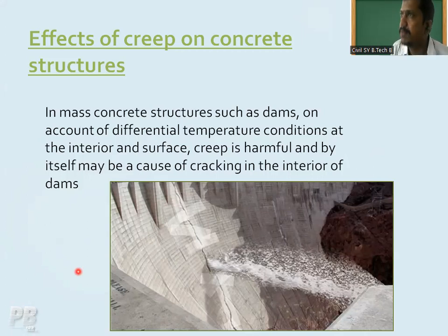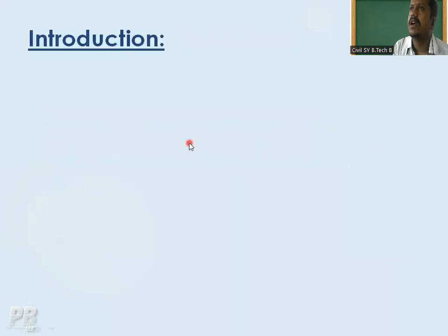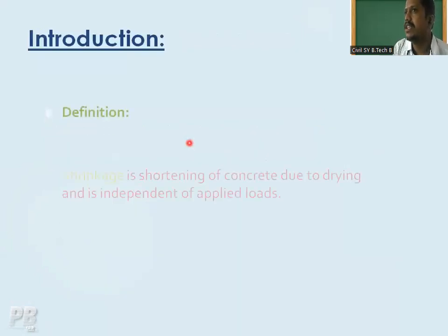But if you follow some faulty practice, there is a chance of early formation of creep, that is early deformation of your structure, and early deformation of the structure may lead to crack formation. Okay, this is the best example you can see. Now the next part is shrinkage.